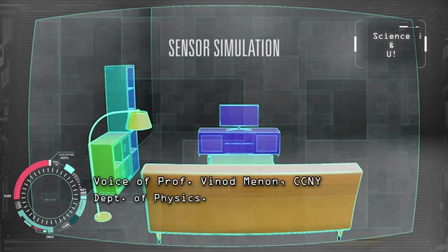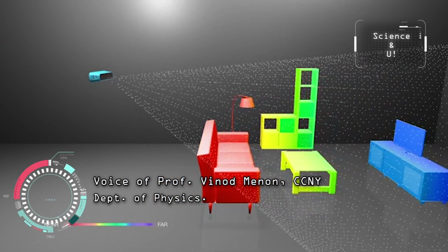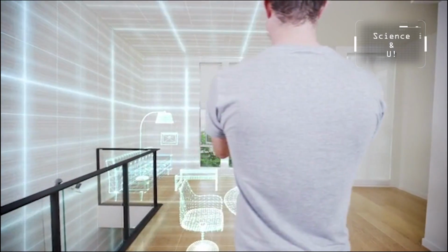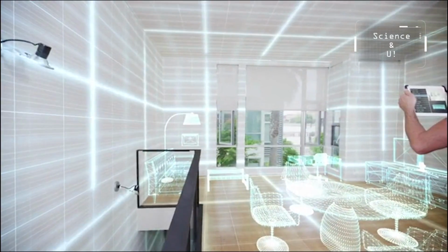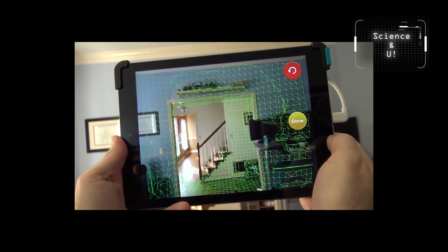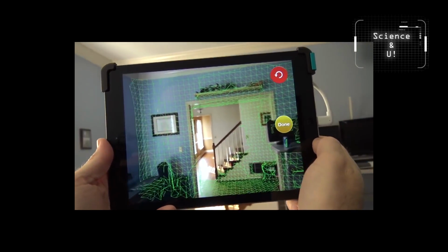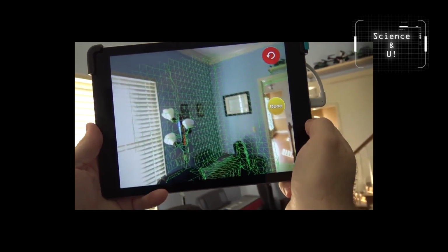So in addition to the infrared camera, it also has a structured light projector, which is probably an infrared laser or an infrared LED, which projects a grid onto the free space. And any distortions in this grid is what is recorded by the infrared camera, which then translates that to depth information. Combining this depth information with the visible camera's data, you get the entire 3D picture.